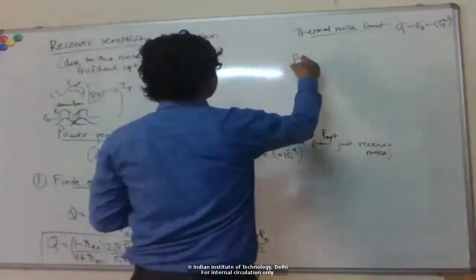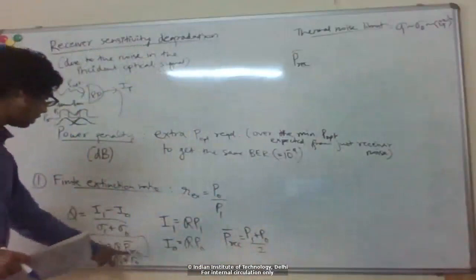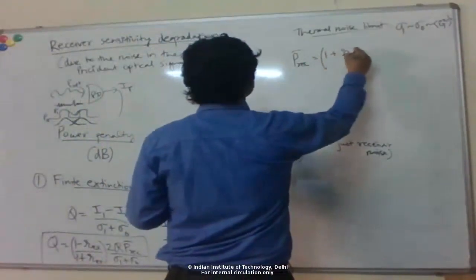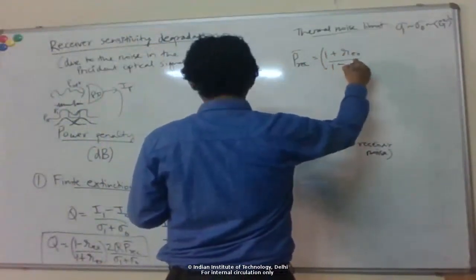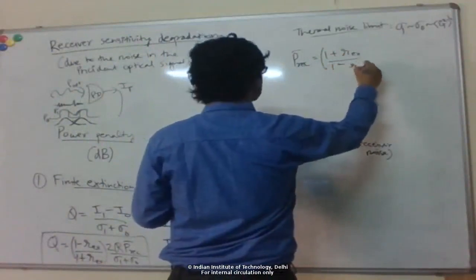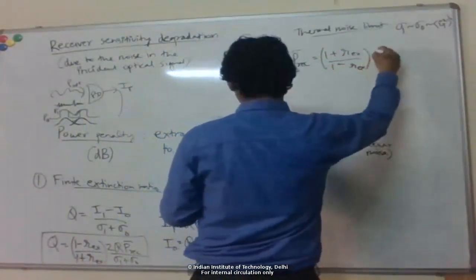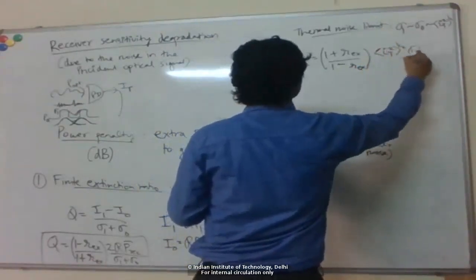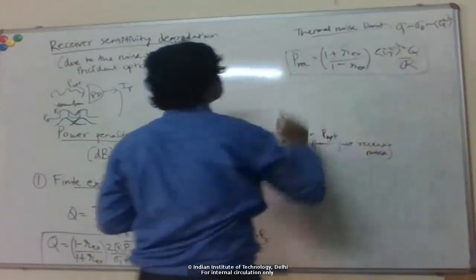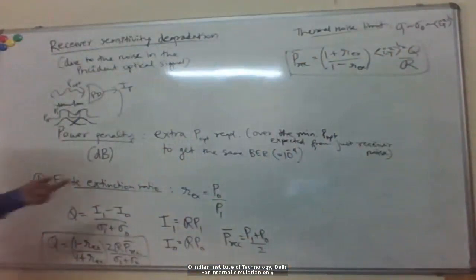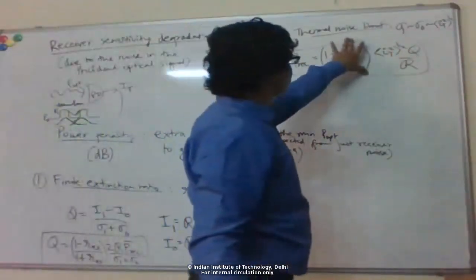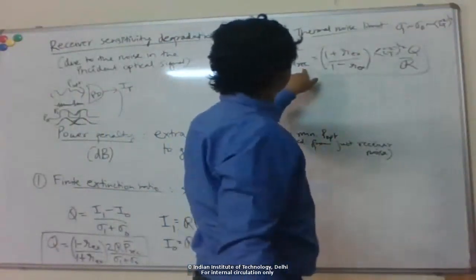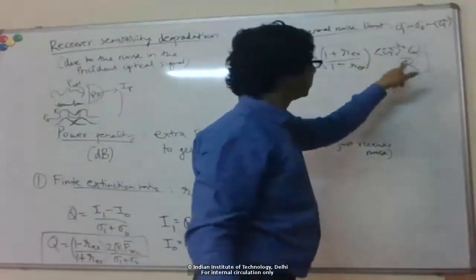Okay, so basically I can write this received optical power in terms of the extinction ratio and the Q factor like that. Okay, so we already saw the case for R equal to 0. So this factor was 1, right? And we saw that in the thermal noise limit, the receiver's sensitivity scales with Q linearly like that.